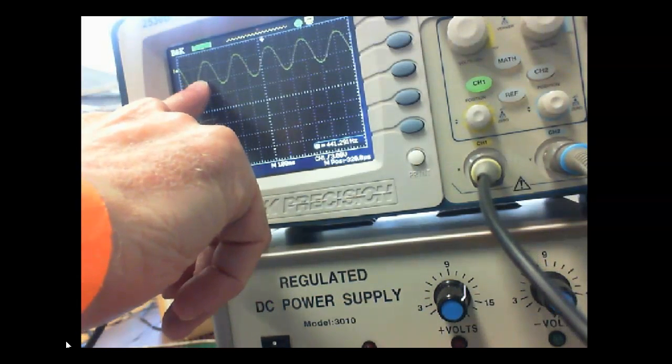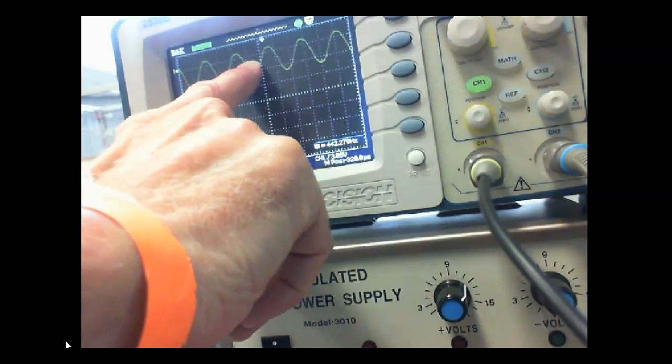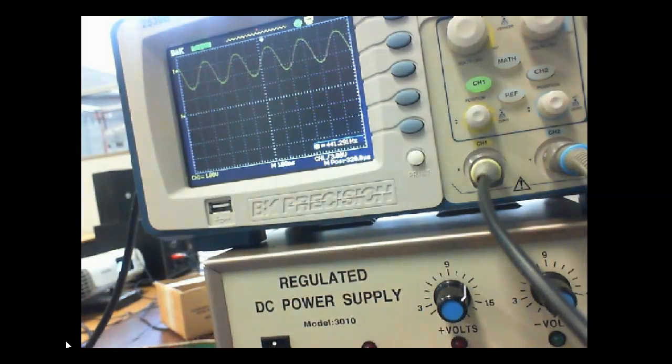Here's my AC signal coming through my capacitor. So what I'm doing, I bring it to the capacitor, and it's actually adding to and subtracting from the DC. So how did I do that? Well, I brought it in through a capacitor. It blocked the DC, kept my 2.5 volts there. But when I measure it with a meter, even though it's got that signal on there, it's still going to measure 2.5 volts.